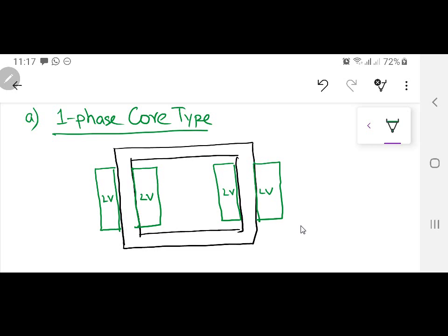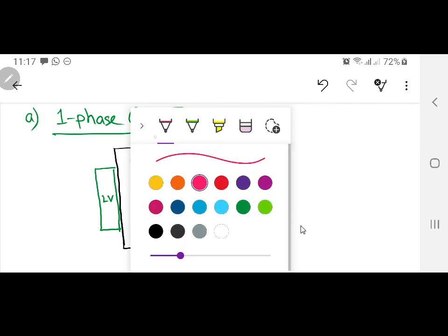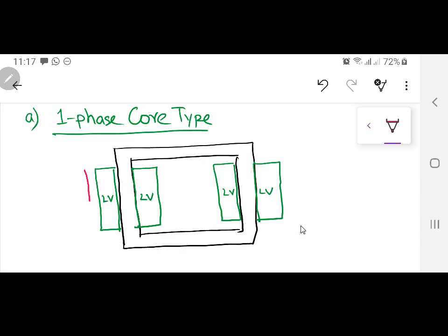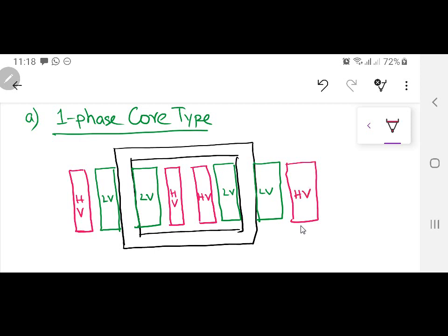अब last lecture में मैंने आपको बताया था कि low voltage winding एक limb पे करेंगे, high voltage winding एक limb पे करेंगे, but you can bifurcate it on both limbs so that the magnetic coupling between the windings is better. So here I have the low voltage winding and then there is a small duct. This is the high voltage and then this is the high voltage winding.